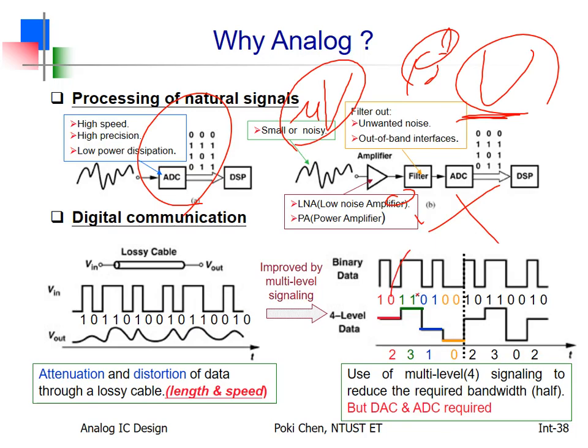Okay. So from the signal in the air to what you can look at or listen to, how much do you need to amplify? Almost 6 orders. You need to amplify the signal by 6 orders, 6 zeros. How can you make that? First of all, we need an amplifier, right? But especially an LNA, low noise amplifier. Why? Because the signal is really, really small.